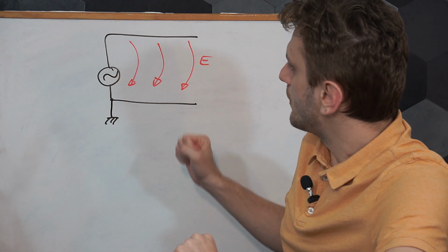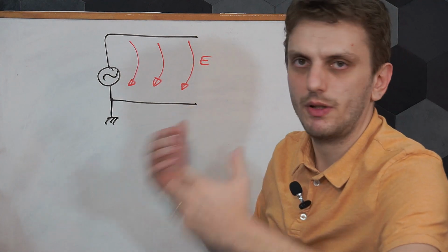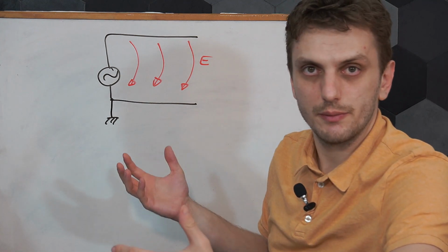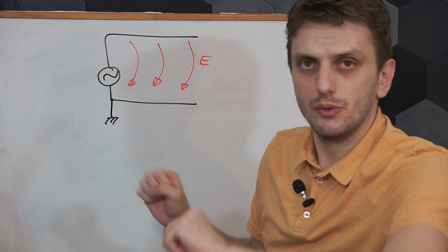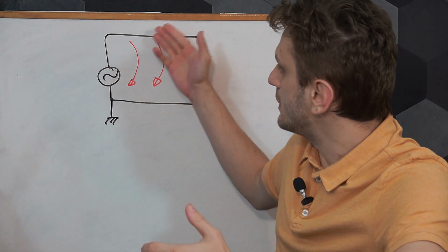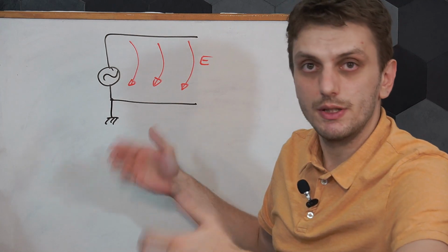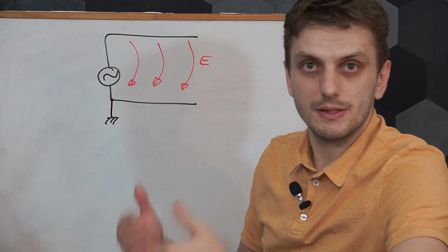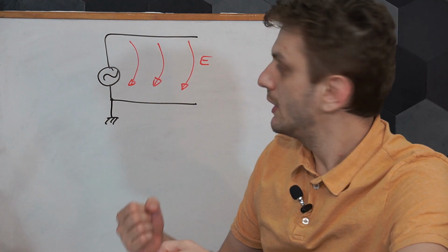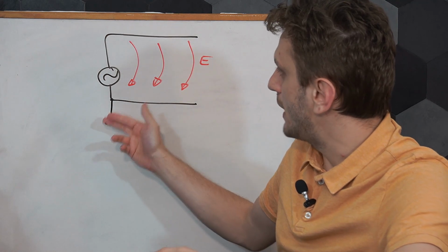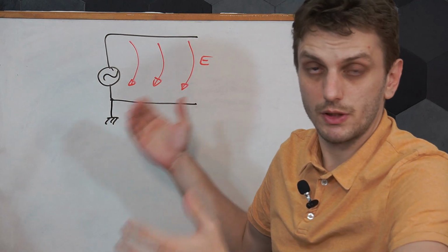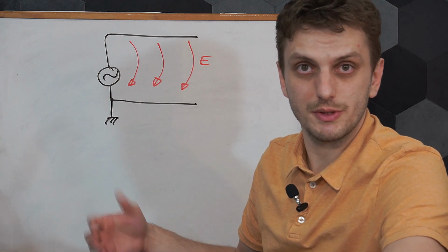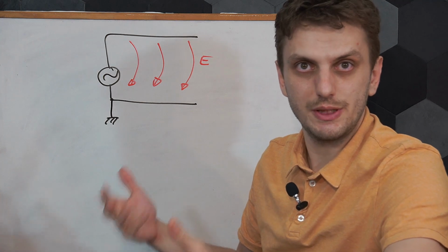Now it's important to observe that between the two conductors there's certain capacity. So the electric fields are mainly capacitive phenomenon. And what's important to notice about this is that the equivalent impedance of a capacitor is frequency dependent. So the higher the frequency, the lower the impedance of the capacitor is. Meaning that if there's a certain current passing through these electric fields, the current will be stronger with higher frequencies. So you will start to have more and more problems because of electric fields as frequency increases.